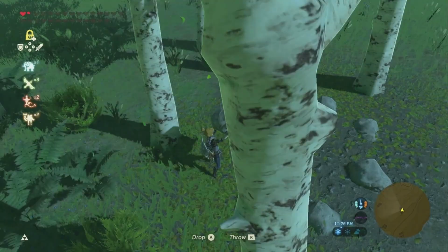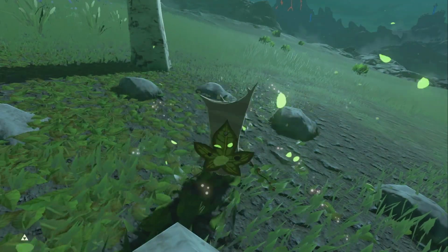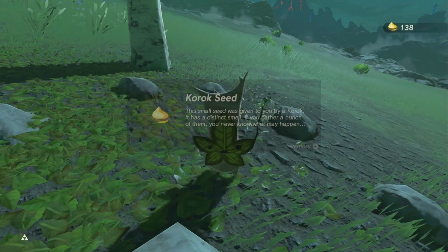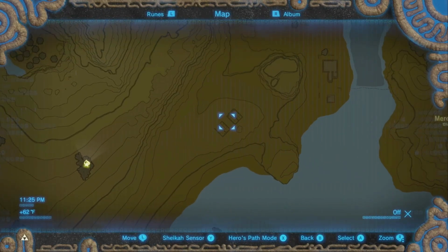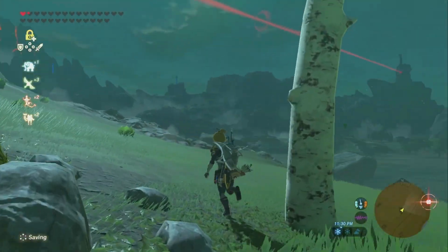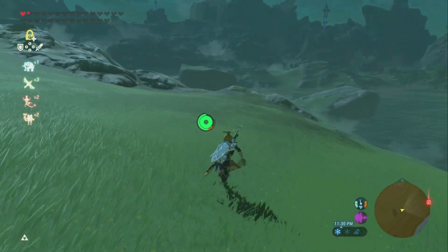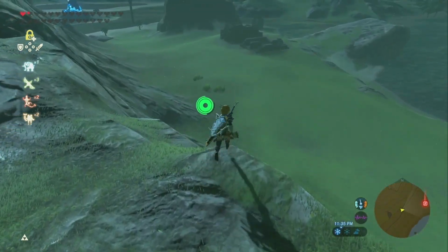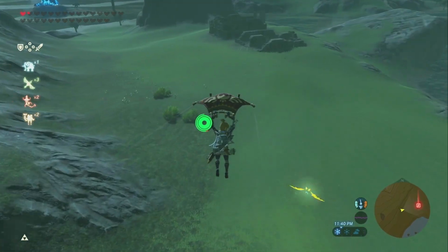Causes. Let me scroll down so I can read all of this. A missing burner cover or heat rollout shield is an installation or maintenance issue. A damaged burner cover or shield is probably the result of careless handling or working around the water heater. A rusted cover or rollout shield may indicate leakage, condensation, or wet ambient environments.